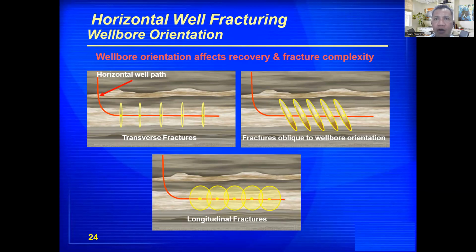This would be if you drill the wellbore not parallel to the minimum and not parallel to the maximum. But say you drill it halfway in between, then you would have a pretty big frac that will initiate and turn, because Mother Nature ultimately dictates what is going to happen. And finally, here's a little drawing of a longitudinal frac where they've come in and done 5 fracs. But again, your reservoir drainage is quite a bit less.